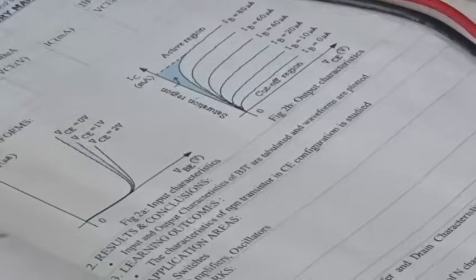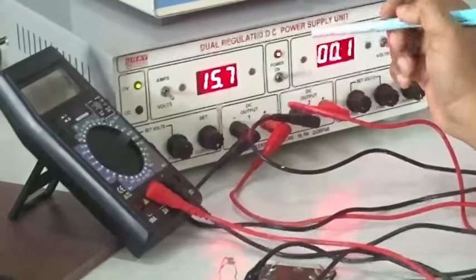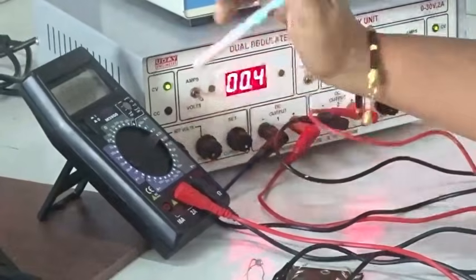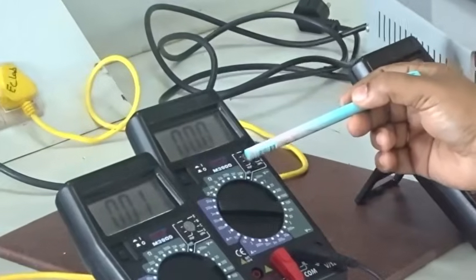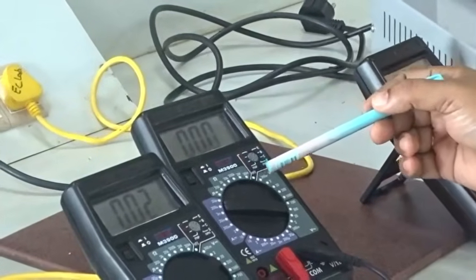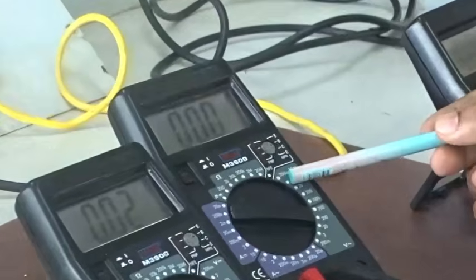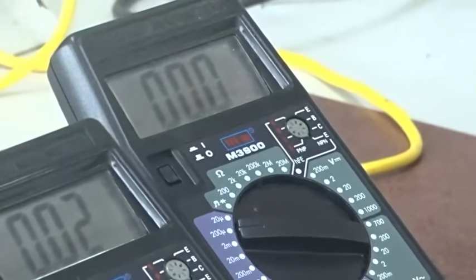And next, the output characteristic. So the procedure for output characteristic is, you need to keep the input current constant. So what is the input current here? IB is the input current. So let us make IB, see, this is our IB. We have to keep this constant. So let us take 3 different values. IB is equal to 20 micro, 40 micro and 60 micro, and you are going to observe IC and then VC.